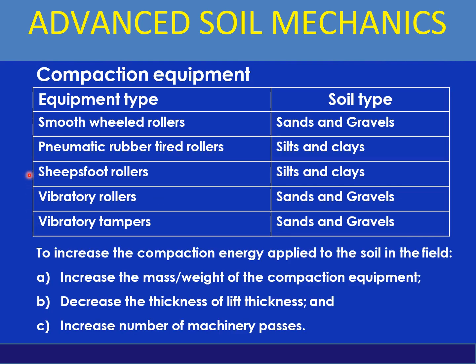So here you would find some summary. Smooth wheel rollers are best suited for sands and gravels. Pneumatic rubber tire roller, silts and clays. Sheep foot roller, silts and clays. Vibratory rollers, sands and gravels. Vibratory tampers, sands and gravels.